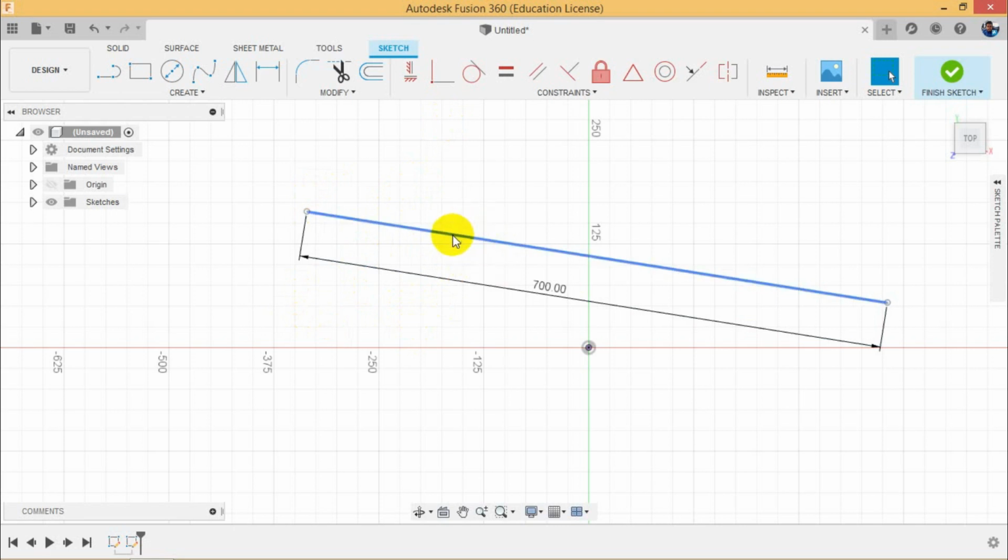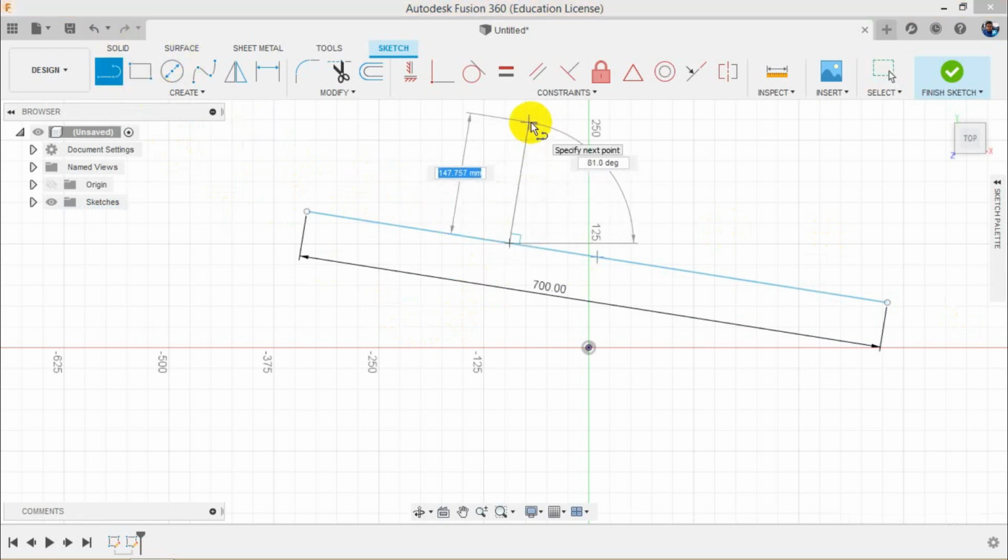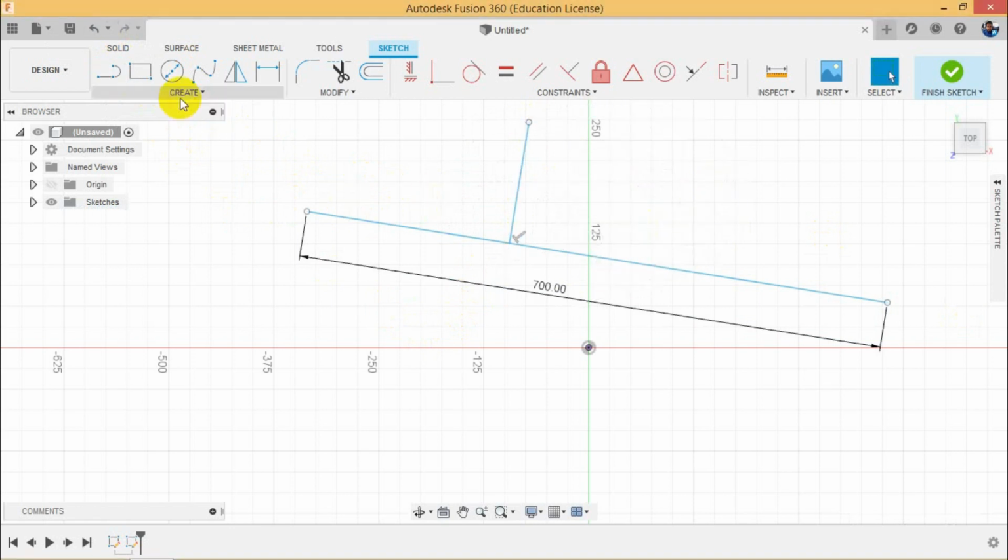We have only two ways to delete or terminate a sketch entity or sketch element. One, you need to click it and then delete it completely, so the entire thing will be gone. Another, you can trim it. How can you trim it? Let's say I have a line in here, and that is intersecting this line also, so that is 100.